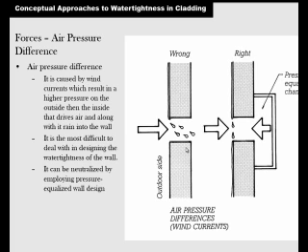Then you can also make a pressure equalization chamber, which we'll see in some detail specifically in a little bit. So you've got your outdoor positive pressure and your indoor negative pressure. So this is a little chamber that equalizes the pressure so that the water won't just flow into there. It'll hit this pressurization chamber and it will just fall straight down. And that's especially important in the taller buildings.